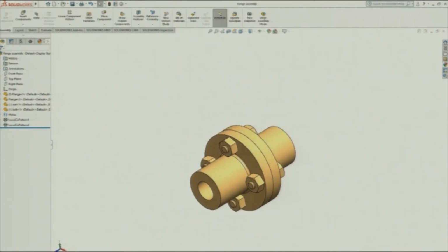For the appearance, there are certain complex assemblies where we need to see the different components. This coloring pattern can be used when we have a big assembly with different parts meeting. We can show the components or parts with different colors. For instance, if there are different sizes of bolts, we can show all the bolts of 5 mm with a green color, all the bolts of 10 mm with a light green color. Components made of different materials can be shown too: grey color for steel, a little brownish color for copper.